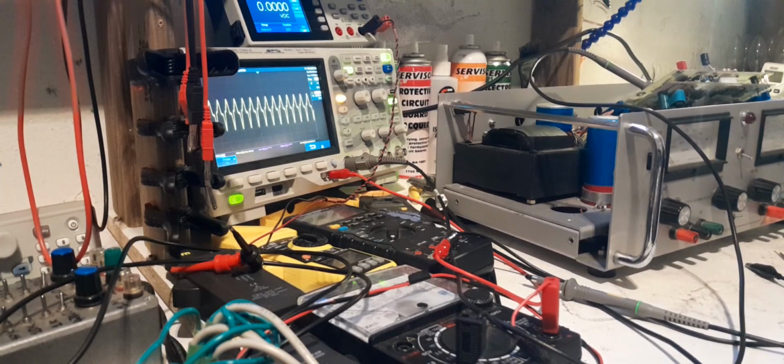And the reason for that is to go across the input pins. Obviously, this will be useless going from the output to the non-inverting input, given this scenario. But just for high frequency suppression without coupling everything else from one pin to the other, this sometimes does the trick.